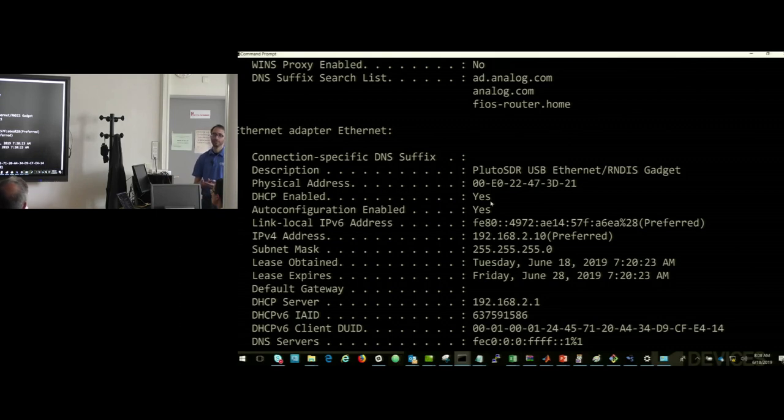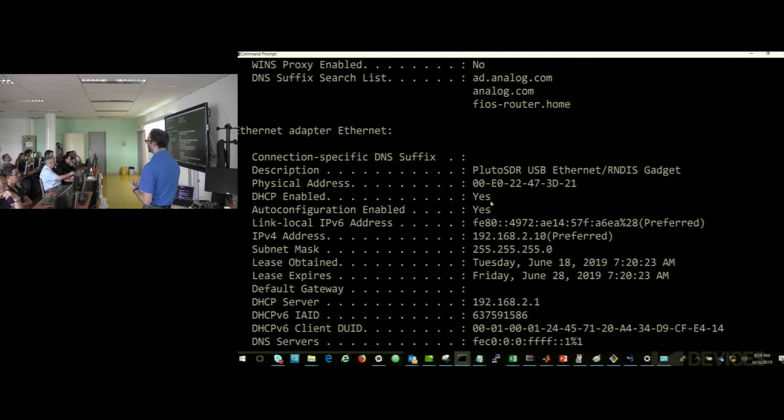And one of the reasons we did this is for virtual machines. Whenever you set up a virtual machine, they're always going to have networking working. It's just the first thing you need to do, apt-get install something. And USB can be a little bit on the flaky side in general. So network is an obvious thing to have on the device. And this works through a tethering protocol called RNDIS. This is actually a Microsoft standard and is available in the Linux kernel as well.